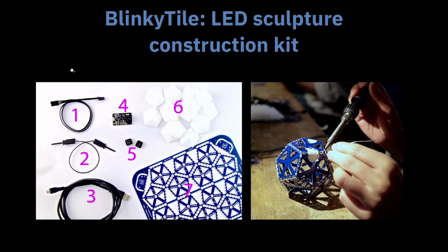We started making these geometric PCBs in 2014. We launched this project called Blinky Tile, and we did a little Kickstarter for it. And this was a series of pentagonal boards on a PCB. Each board had one LED, and the shtick was that when you solder it together, the soldering points are also making the connections. So you can form the structure just as you're soldering it together.